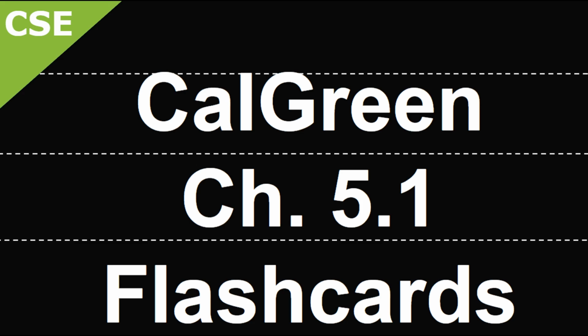Let's review an example. You have 55 actual parking spaces. We know from the previous calculation that we needed 3 electric vehicle supply equipment spaces, or 3 electric vehicle charging stations that have that capacity of an EVSE. In the power allocation table, separate than the previous table, which we used to determine the number of electric vehicle spaces and electric vehicle charging stations, this table, you must find the row where you have your total number of actual parking provided, in our example 55, and read across that row.